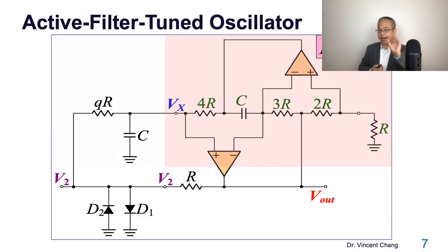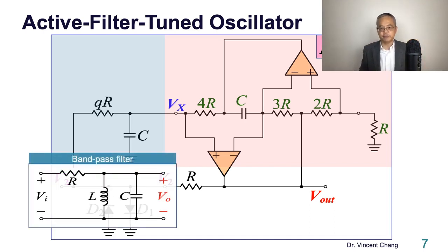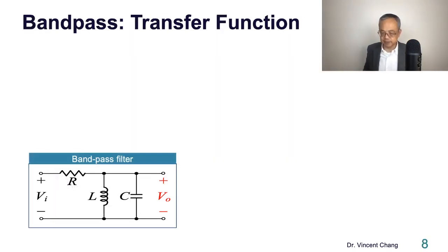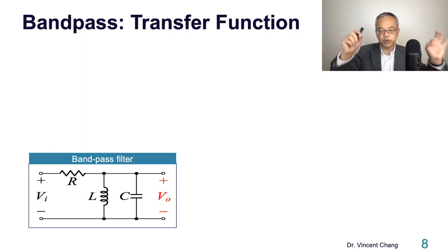You see a bandpass, right? Now you see the equivalent inductance. Combining this inductance with its neighbor, the capacitor, and also the series resistor qR, with the lowercase q, these three generate a bandpass function. So this is the bandpass filter, the R in series with the parallel combination of the L and the C. Let's quickly go through several important characteristics of this second order bandpass function.